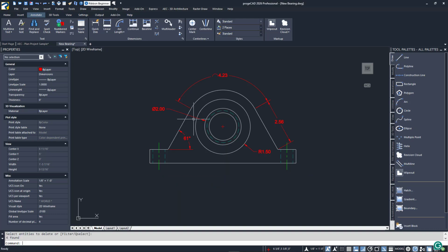I've left out one of the tools in the panel, and that's QuickDim. It's a tool that can be quite useful in the right situations, but not always. With it, you define the entities to be dimensioned with a crossing or inclusive window. It will literally find all of the geometric points it can, dimension, and create the strings for you.